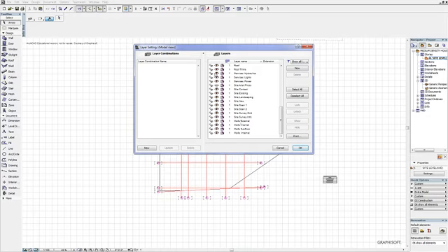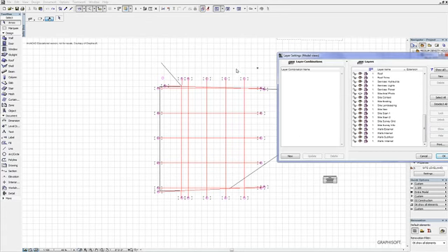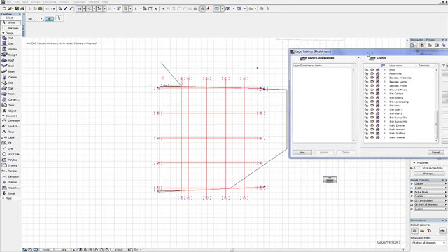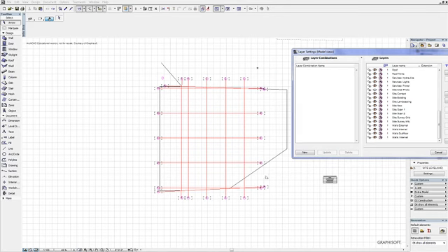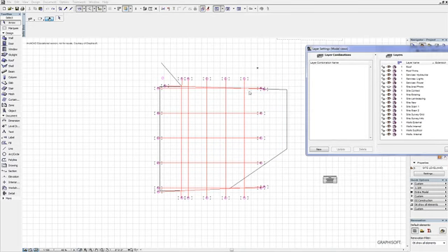At the moment, I have the Site Aerial Photo layer hidden, which is indicated by the eyepiece being closed, which means that anything that is allocated to this layer is not visible in our working grid. The reason that I hid it was just to make my drafting on the grid easier, because I didn't want this photo to get in the way of what I needed to be drafting. But now we really want to see this photo so that I can understand what the roof shape is doing on the adjacent property.